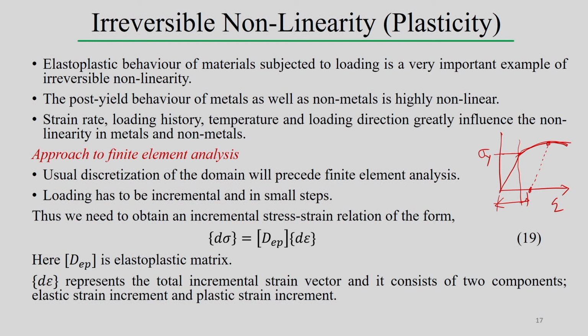So, for a small increment of the strain, we can calculate the associated increment of the stress by looking into the constitutive relation between the stress and strain, as well as the relation between the displacement and the strain field. We use all these relationships, but the analysis can be done in the incremental mode because of the nonlinear nature.